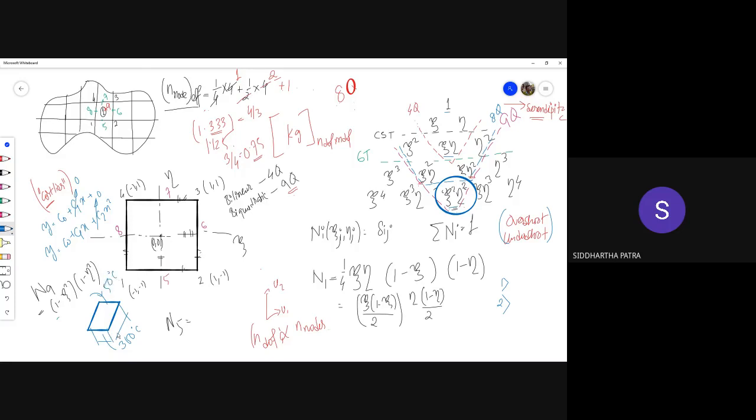In a simple conduction problem like this, nowhere in the geometry should the temperature go below 50 degrees Celsius or above 300 degrees Celsius. With serendipity elements, you can have a solution where you end up having overshoot and undershoot, that is, temperatures below 50 degrees Celsius and temperatures above 300 degrees Celsius within the geometry.